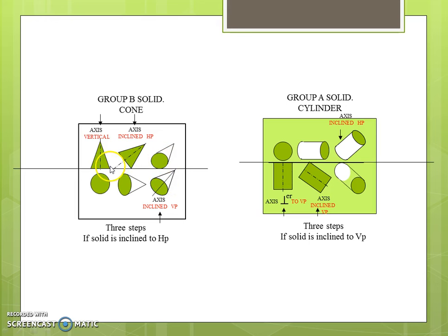Already we have discussed that with inclinations, the solid may lie on one of the corners, or one of the edges, or one of the generators. Here it is resting on a corner. So we are tilting such that one corner will be on the XY plane. Here also it is resting on a corner. So this corner we placed on the XY plane. Similarly, if a generator is resting on HP, then this total generator we have to draw on the XY plane. Like that we have to consider the positions and draw the projections of solids.